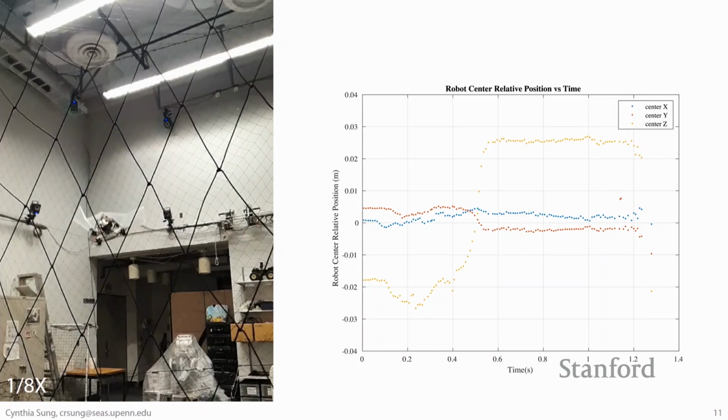So we were really excited about this because we said, well, okay, we used topology optimization to automatically design these compliant arms, which allowed us to get basically passive switching between modes for this hybrid aerial vehicle. And we didn't have to add any additional actuators other than those that were already on the vehicle, right? All of this transition was achieved just through acceleration, just through the control.